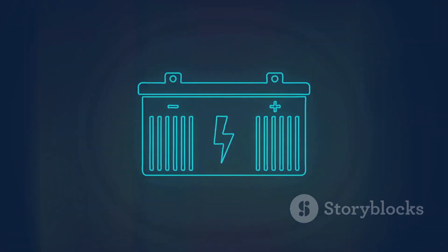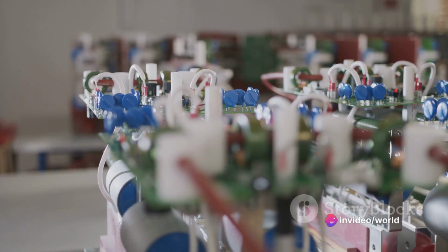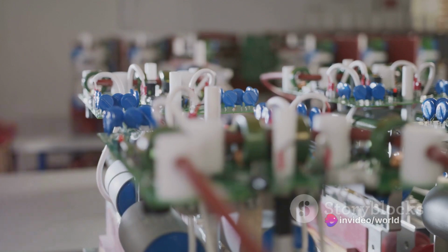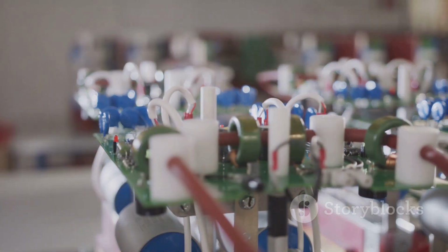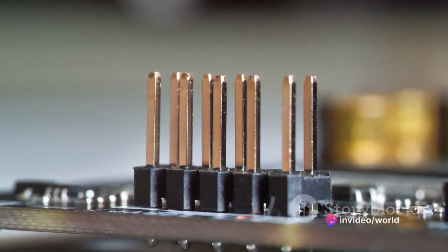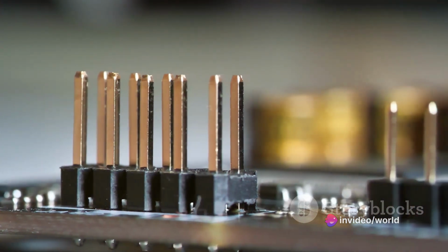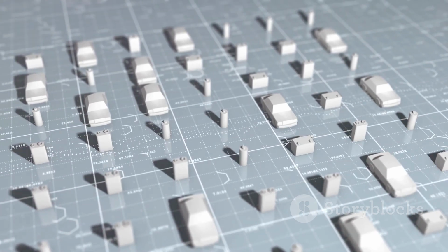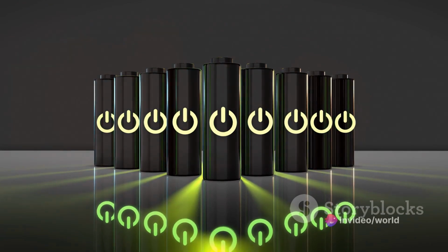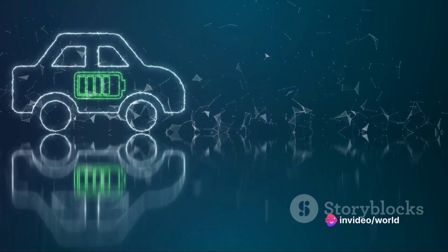Now let's touch on different capacitor technologies. These include various materials and designs used to enhance performance. For instance, some capacitors use high permittivity dielectrics for increased capacitance, while others may use low-loss materials for high-frequency applications. Next up, nanocapacitors. These tiny capacitors offer high capacitance in a small footprint, making them ideal for use in miniaturized electronic devices. Last but not least, pseudocapacitors. They bridge the gap between supercapacitors and batteries, offering high-energy storage like batteries and quick charge-discharge capabilities like supercapacitors.